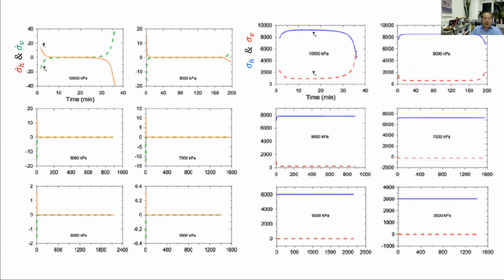Yeah, they do change. The thing here is, in order that the stress rate becomes 0, so if you got here blue and green, one of them is the kind of rate independent, the other is rate dependent. If you see, if the rate independent part reduces, rate dependent will increase, right? So the sum of these two must be equal to 0. So if you see everywhere, right? That is for the stress rate, and that is for the stress. So it's pretty interesting, right?